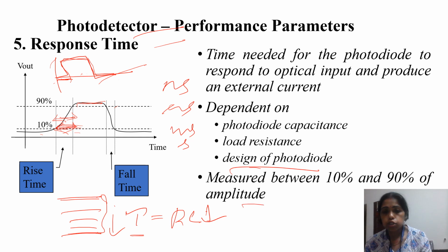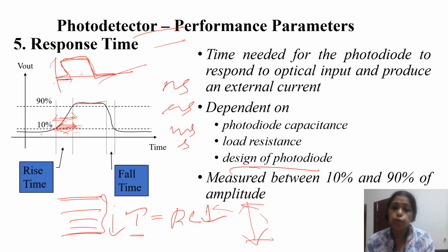If you are using a high thickness device, it will impact the capacitance, which in turn will change the response time. There are some other different factors that are important for fabricating the device, and if you measure them, you can evaluate what the main design parameters are that influence the capacitance as well as the response time.